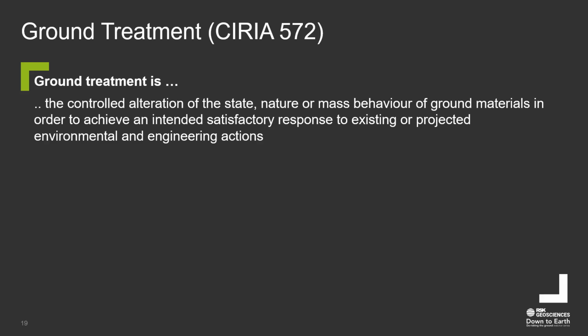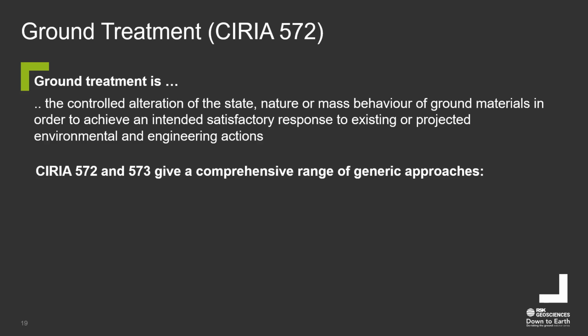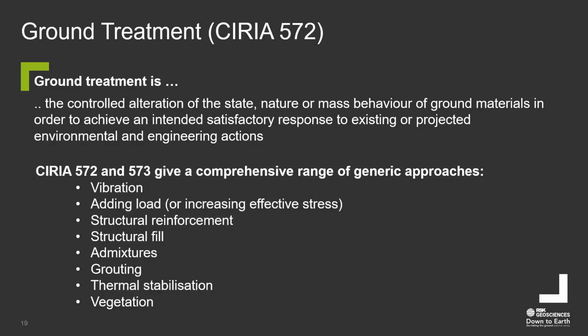It's quite an interesting thing, this, that the ground is what it is, and if we need to use it, then we may have to change it. So we've got quite a powerful responsibility here to try to come up with a way of using this soil rather than just throwing it away and bringing in more material from somewhere else. And the comprehensive range of approaches that CIRIA 572 and 573 published is a big list, which primarily talks about agitating the soil or adding load.